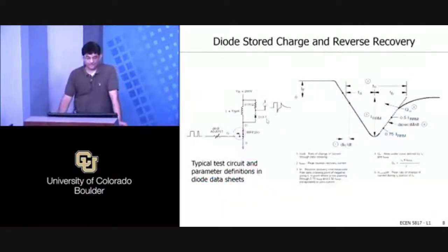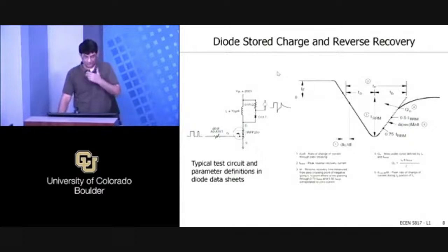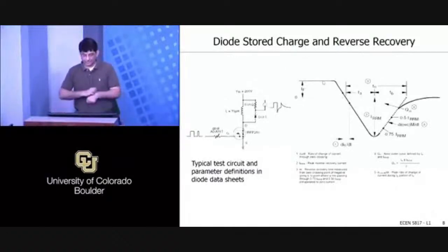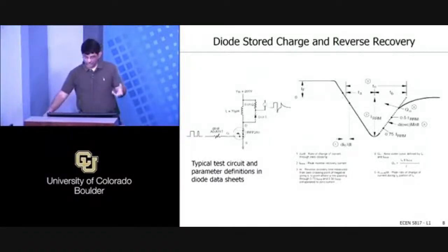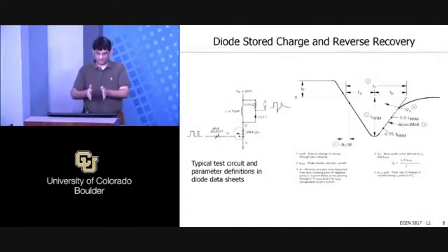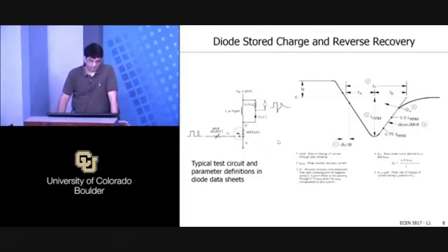I want to say a few words next about the diode, because you're going to have a homework problem where you'll actually be solving a similar kind of problem, but not with a snappy diode, but a soft recovery diode. A snappy diode is where, as soon as you remove the charge, you've reached the point where the junction can start blocking, essentially all the charge is gone, and suddenly the voltage will rise across the diode.